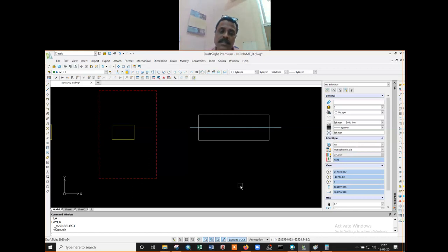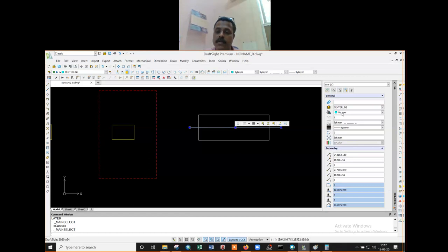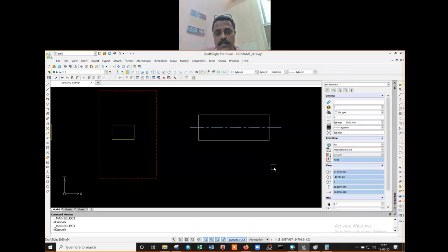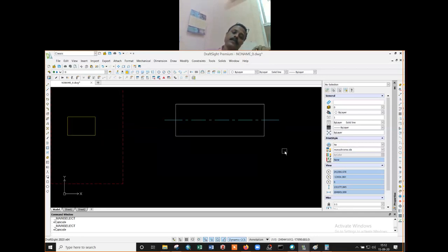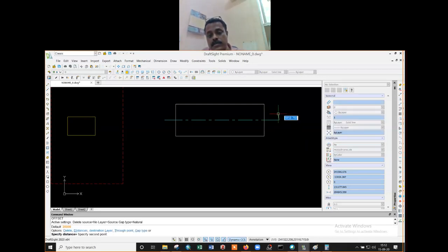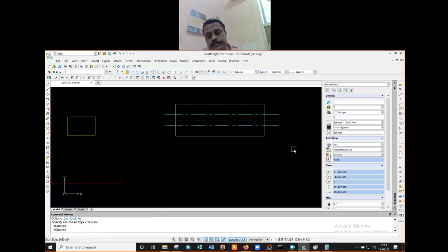But again, you cannot see the center line. Why? Because the scale is not enough. So you click one more time, go to the scale part, then press 10. If 10 is not enough, you go up to 100, then maybe go up to 1000. So 100 is almost showing up. So go maybe up to 500. So you see? This is the center line. So if this is an object that has a hole of a similar diameter, how will you show a hole?